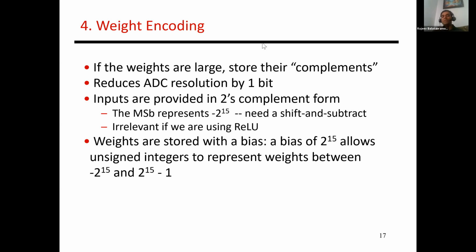Does analog have the same degree of challenges? Yes. And clearly one of the main issues that is brought up with these accelerators is the fact that the error rate is going to be higher, right? When you have these sense amplifiers for these analog signals, there's a decent chance that one of these bits may be off. In fact, the very next question is, can you do error correction on this as well? And I have that coming up on a slide. I can give a little bit more detail when I get to it.